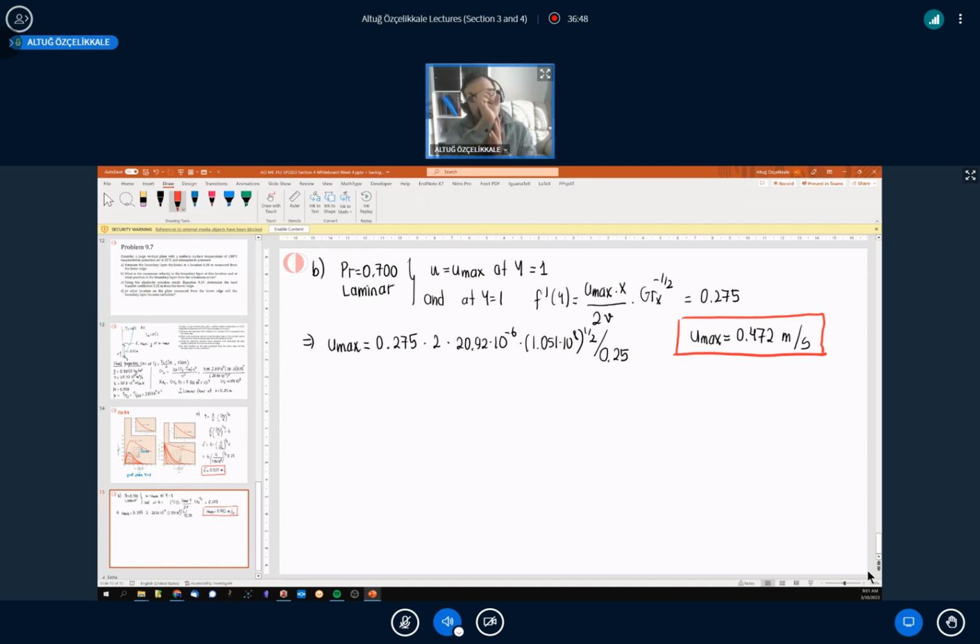So at this particular location, within this thick boundary layer, some part of this boundary layer has fluid moving at about 0.5 meter per second. So it is something like this. Right? You can visualize that a temperature difference of approximately 100 degrees Celsius here is causing that kind of flow phenomenon. It's very interesting. Okay, there is one more question. What is the location across the y-axis? What is the location?